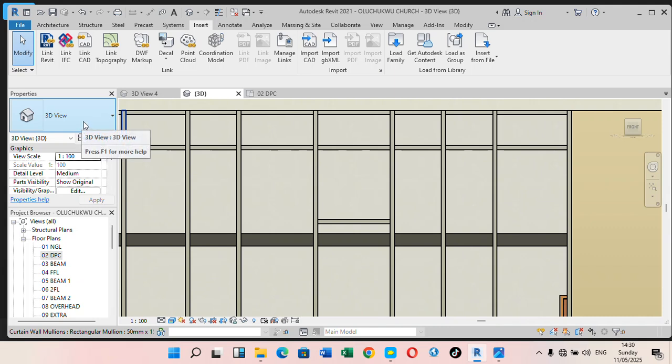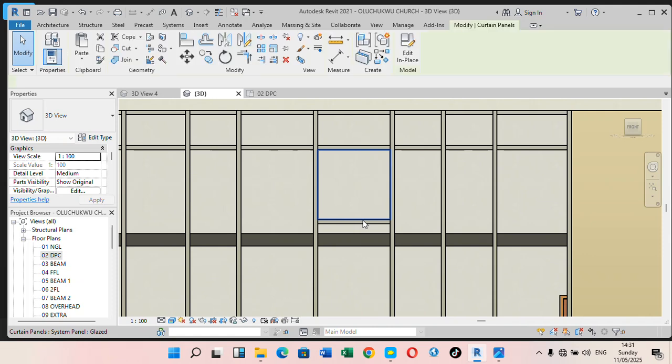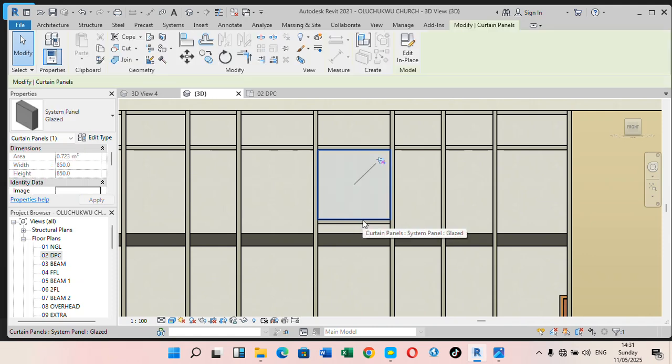So I come here now. But before I do that, I have to come here and select the glass panel. As I've placed this here, I tap on my tab key, 1, 2, 3, then I select it. If it is pinned, you try to unpin it, but as you can see, this is already unpinned.